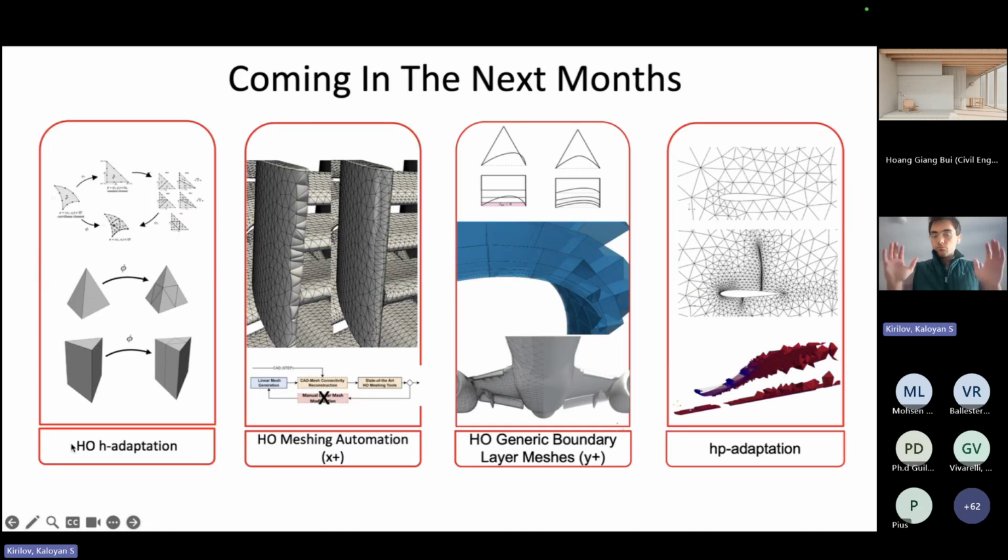We are heavily working on NekMesh. There are several PhDs, and I'm working as a postdoc as well on it. And in the past several years, we have actually introduced high order edge adaptation. We have to merge it with master soon. So in the next several months, we will also give you the possibility to use high order curved edge adaptation, so no need for remeshing. We already did some, we just have to merge it. There is some automation that will actually allow you to do most of it inside NekMesh and not go back to your linear mesh generator if something is very, very complex, like in this case.